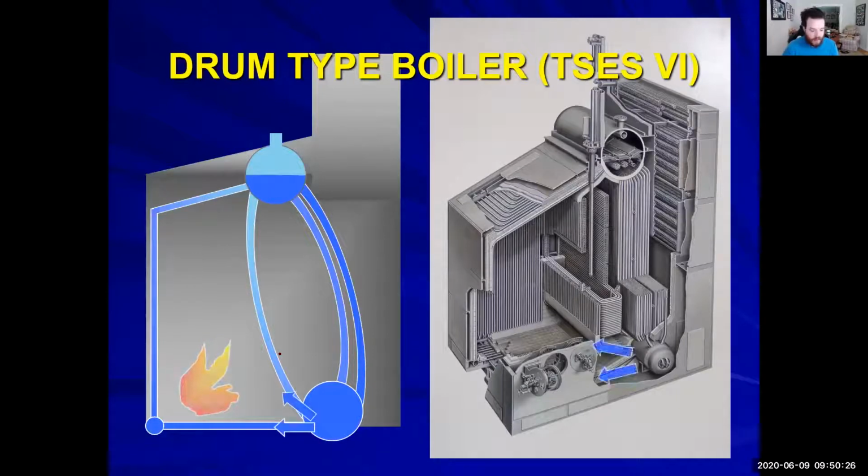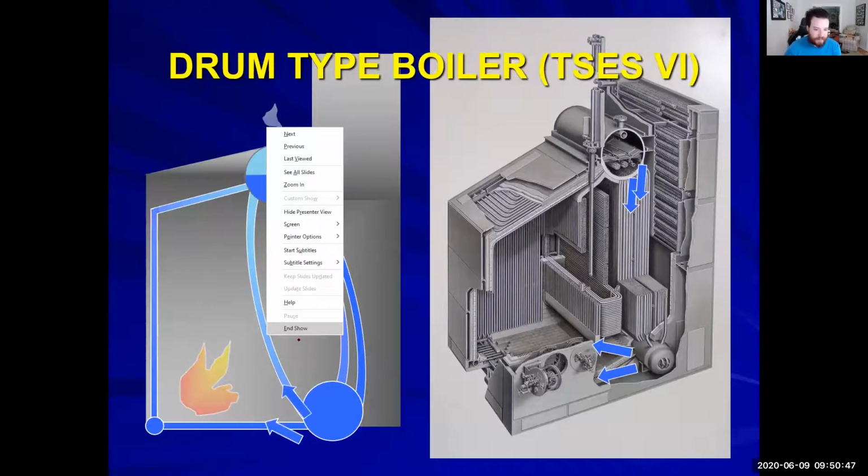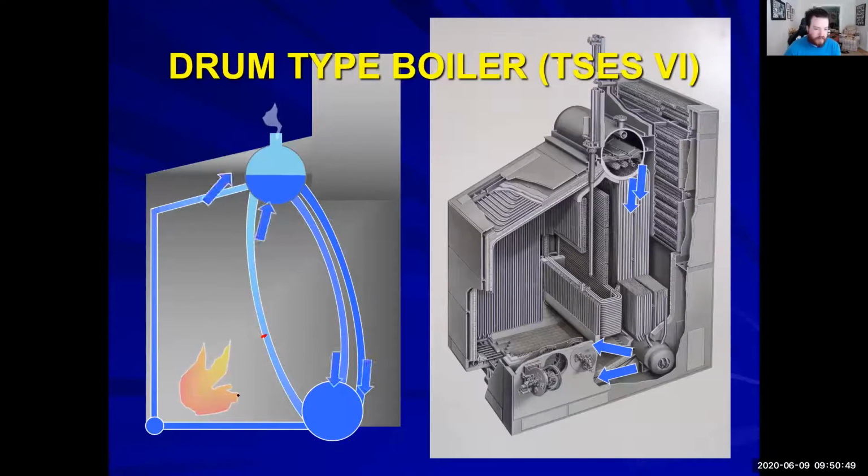So you have a flow of water that happens inside of these generating tubes and these water wall tubes. Basically, they're in this circular motion of sorts. All right. And what's happening is that in certain spots, the flame will come in and a steam droplet forms here. And it would travel up a little bit.